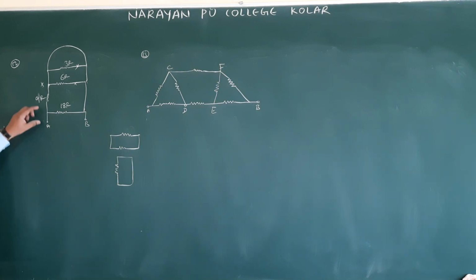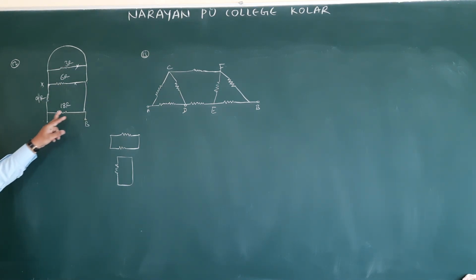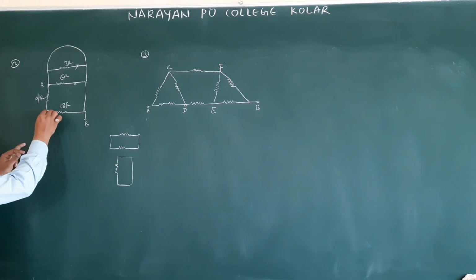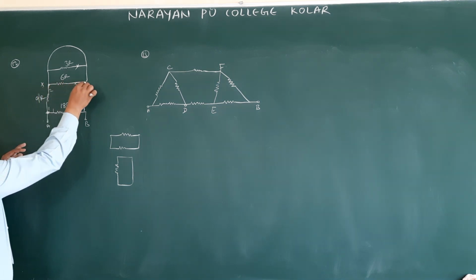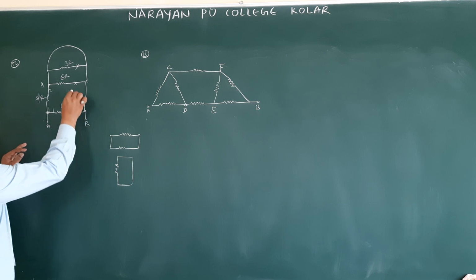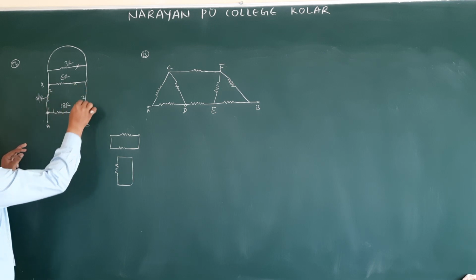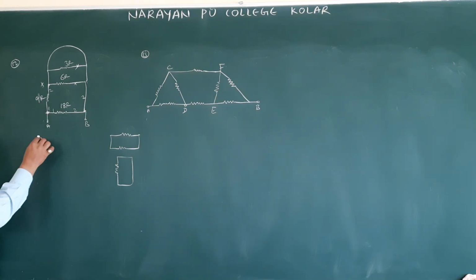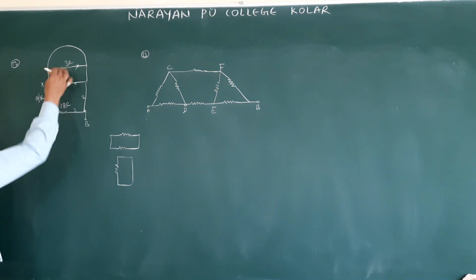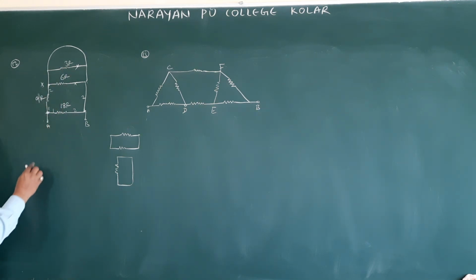So the remaining circuit is this one. If these are also not working, therefore this is 18R here. See here, this 9R, one end is connected here for A. 18R, one end is connected here for A. The second end is connected for B. Therefore, 9R and 18R are connected in parallel. So if you want to draw by removing these two, you can draw. You will get the idea.